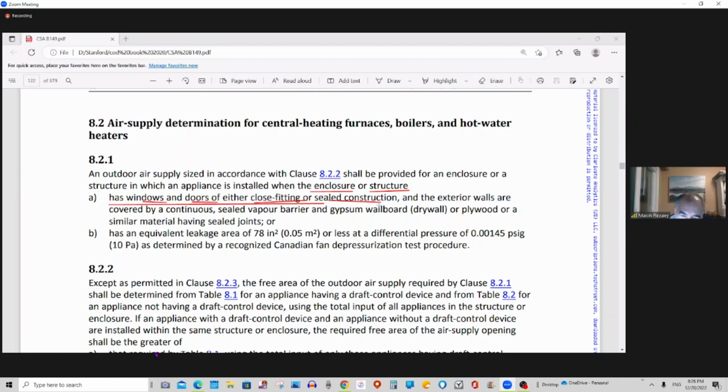Michael, you work in construction, right? Yes, sir. How do you seal door and window? Caulking, or sometimes we use foam, right? Yes, sir. So you put special caulking or foam and vapor barrier. Great. Or we use this tape, the red tape, tuck tape. Where do you put it? You tape the joints, or you tape the edges of the vapor barrier around the window frame, like a picture frame. You know what I mean?